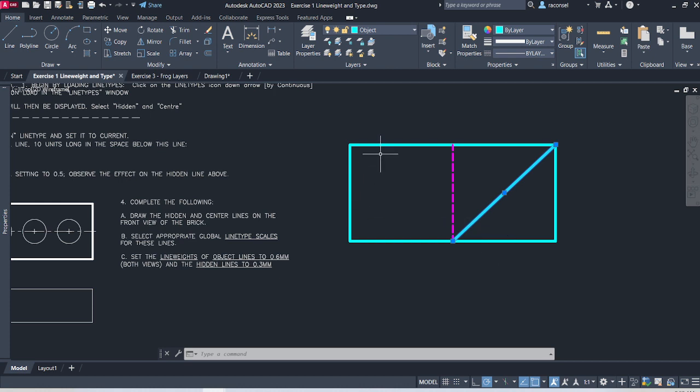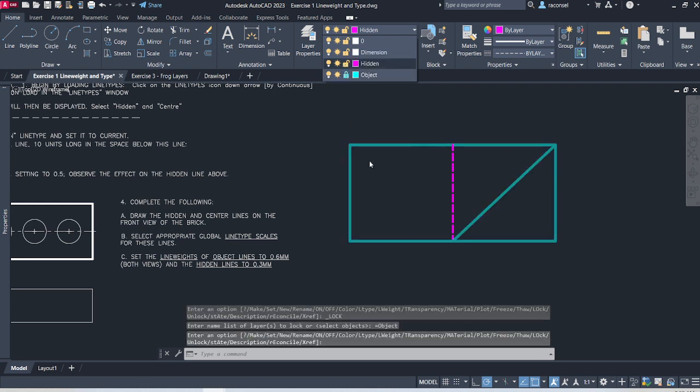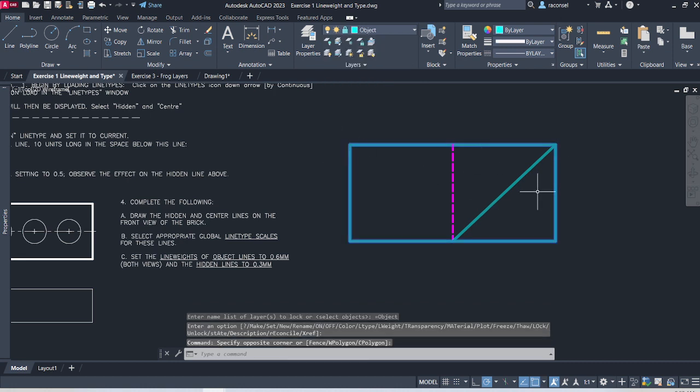Other neat things I can do with my layers. I can lock them. Be like, hey, my object is perfect. I don't accidentally want to mess with it. I don't want to move it around. I don't want to do anything by mistake. Locked. So it fades out a little bit. So all I did was in my little layers drop down menu, I clicked on the lock. So now when I go in here, I can select it, but you'll notice my control handles are all gone.